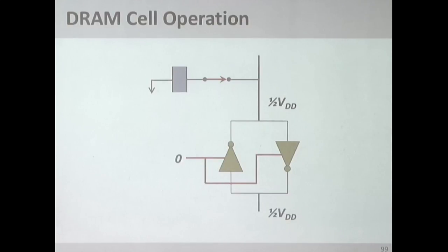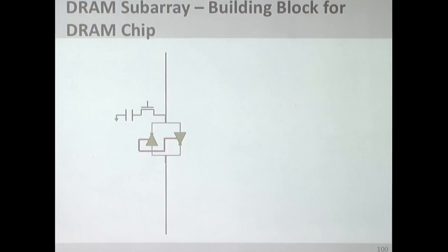It's really a sense amplifier because you can enable and disable it. And when you connect the cell, you basically share the charge of the cell with the bit line, which means that you perturb the bit line slightly because this is very, very little charge over here. And once you perturb the bit line slightly, when you enable the sense amplifier, you get VDD over here. That's how you sense. Right? And then the sense amplifier actually starts driving because it amplifies it, and then you restore the data in the cell. That's exactly how the low-level stuff works.